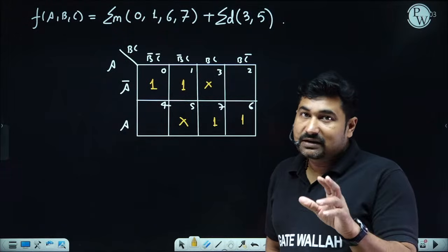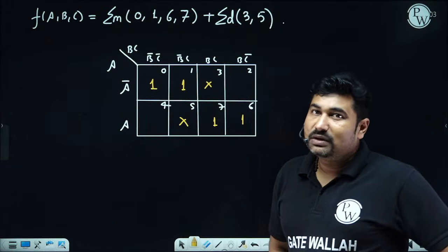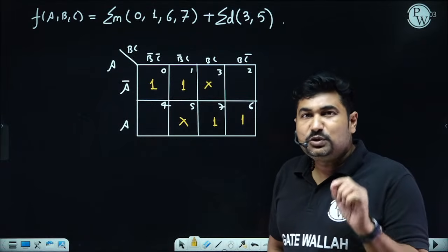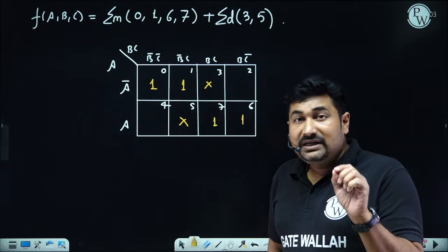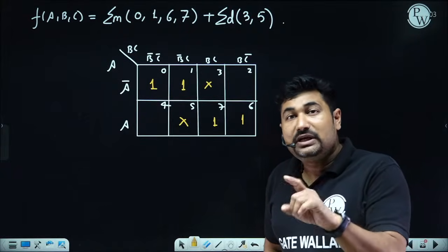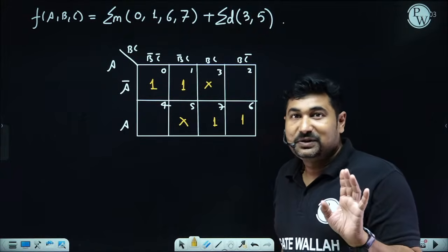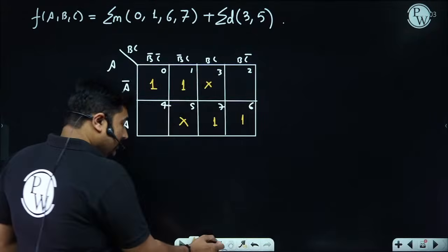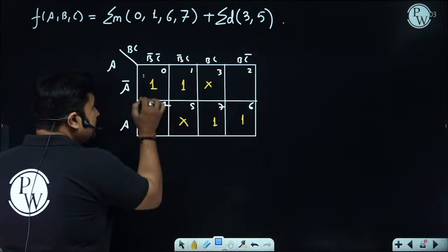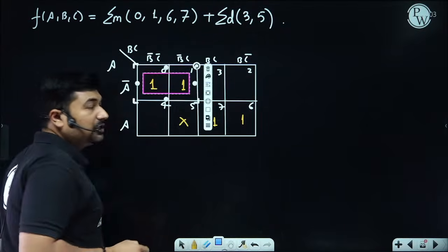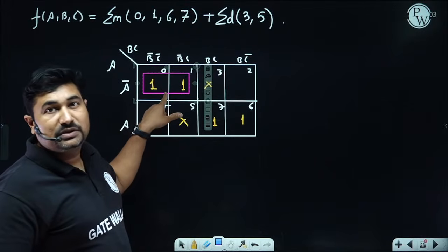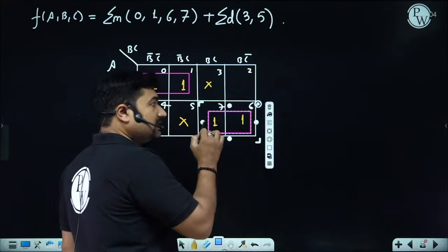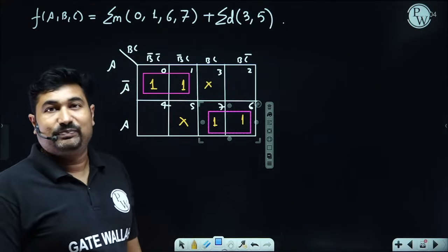Essential prime implicants are not covering that don't care. Okay. So only the groupings of logic level ones. So I started by first finding those min terms which can be grouped only in one way. Those logic level ones which can be grouped only in one way. So when I saw that, we can all see 0 and 1 must be grouped in order to reduce min term of 0. In the same way, in order to reduce min term of 6, this pair is an EPI.